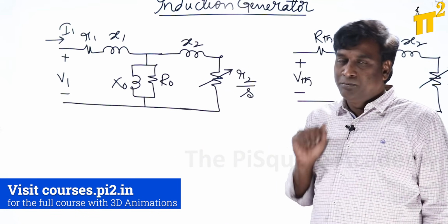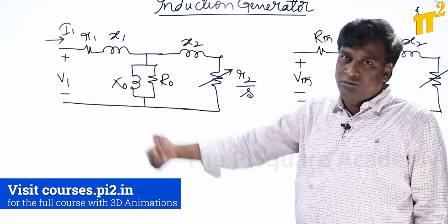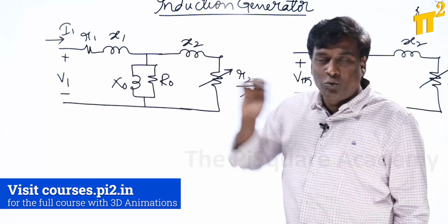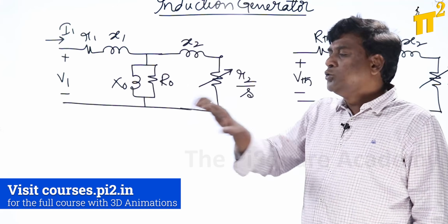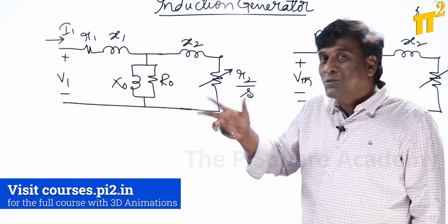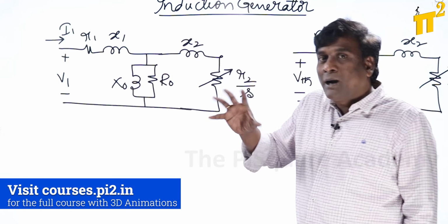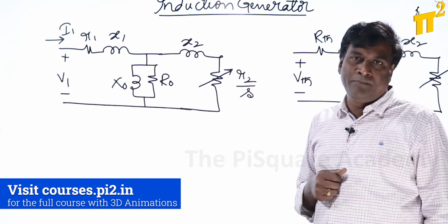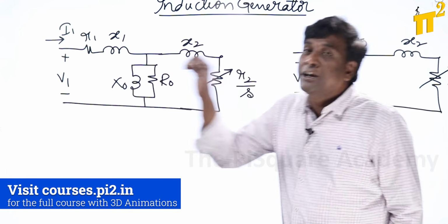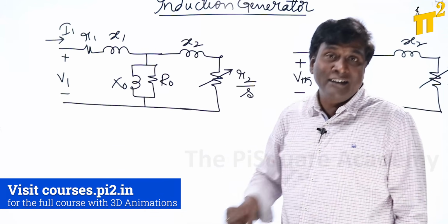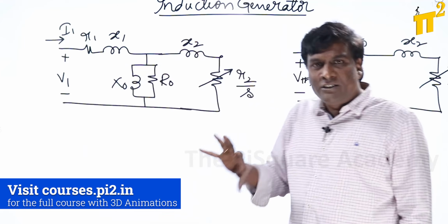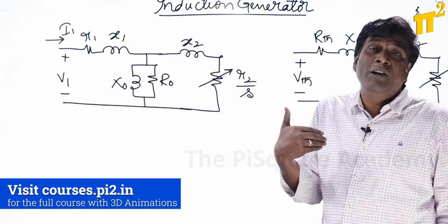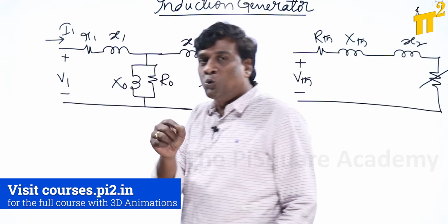Meaning, very simple, see here: stator MMF is rotating at 3000 rpm. Rotor at standstill will try to rotate to 3000 rpm. For example, you release the rotor, and my rotor will strive hard to reach 3000 rpm. Now if I am trying to rotate the rotor by external means, by connecting it to some prime mover, beyond synchronous speed, at 3500 rpm, then again on the rotor some torque will be produced such that the torque will be trying to keep the rotor at synchronous speed.